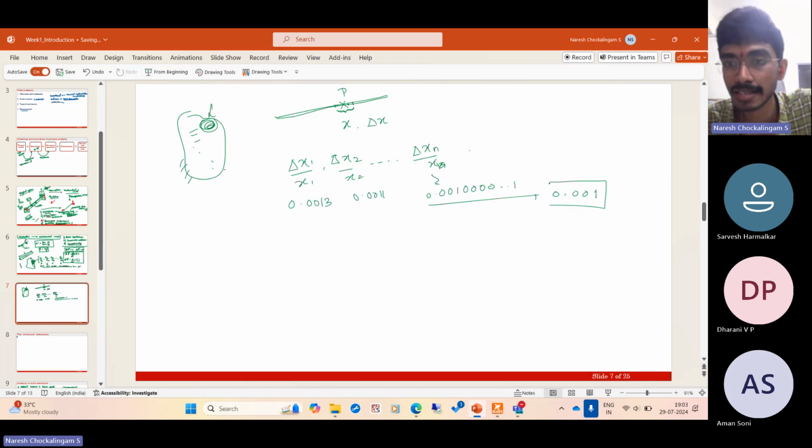You call the strain at the point P the limit of this sequence. As you take smaller and smaller segments enclosing the point and let the length tend to 0, it will never actually become 0, but the ratio will converge towards some limit. That limit is the strain at that point.